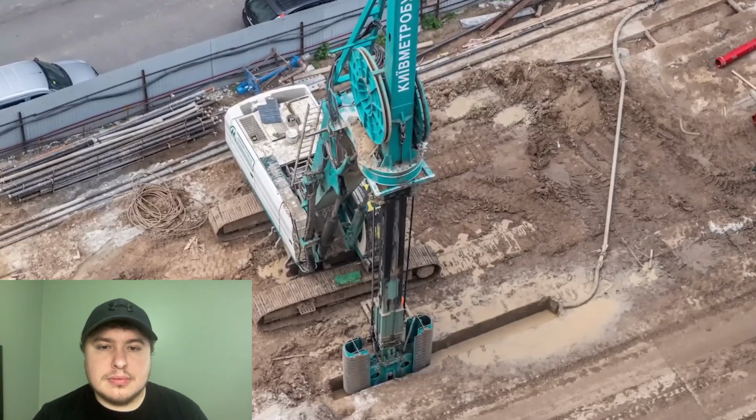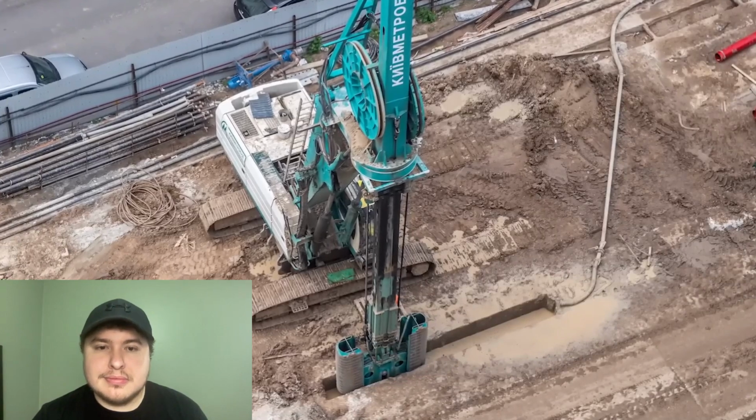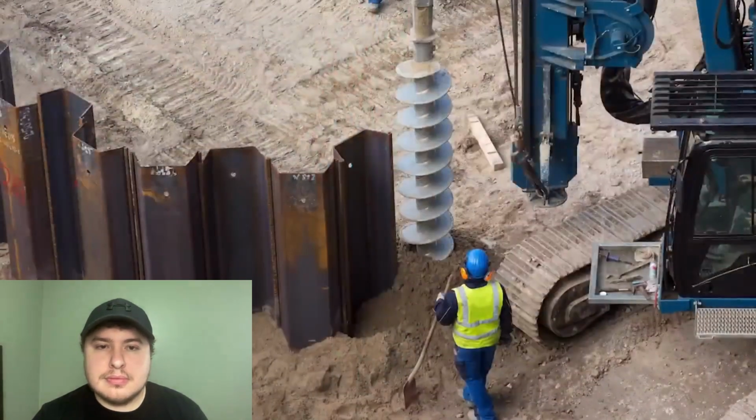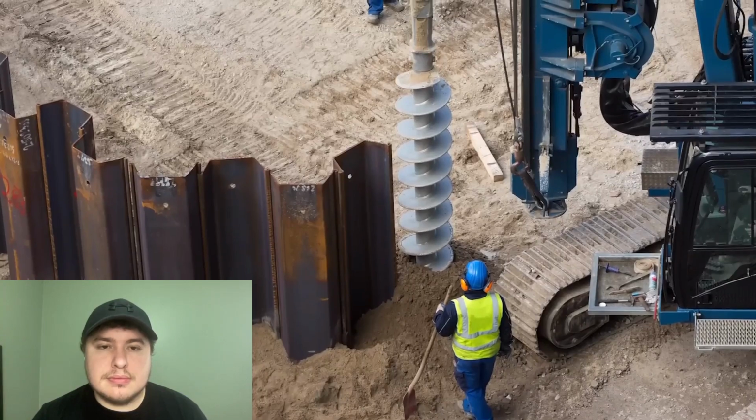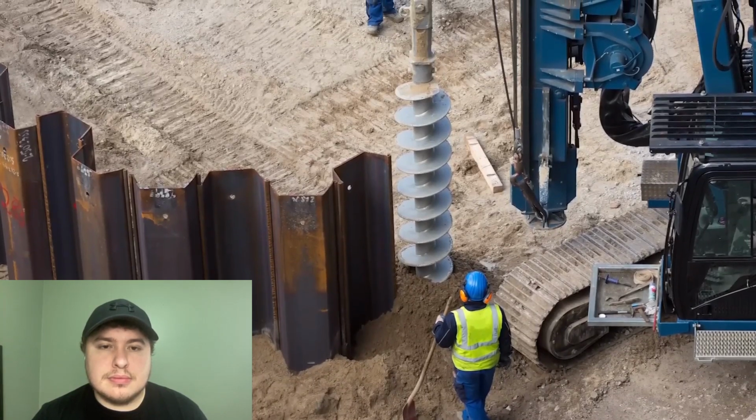Cutoff walls on dams have a long history of use, and nearly all large gravity dams have at least some kind of cutoff. It can be as simple as excavating a wide area of the dam's foundation before starting on construction. And that's a popular choice because it gives engineers a chance to observe the subsurface conditions and make sure there are no faults or problems before the dam gets built. Another option is to excavate a deep trench and fill it with grout, concrete, or a slurry of impermeable clay. For smaller or temporary structures, sheet piles can be driven into the subsurface to create a cutoff. One final option is to inject high-pressure grout to create an impenetrable curtain below the dam.